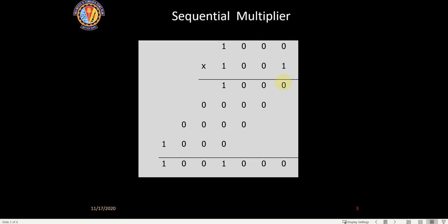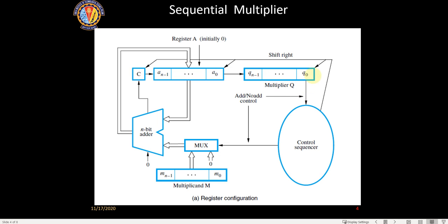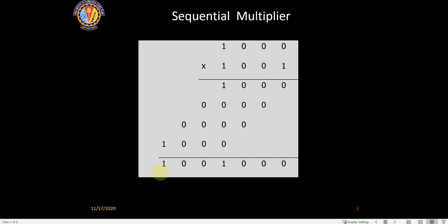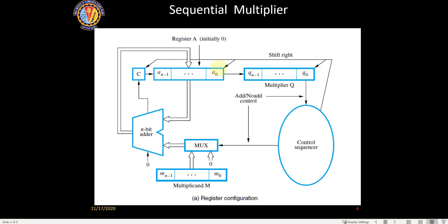So in the third cycle, the third bit is going to be coming here. Likewise, in the fourth cycle, all the 4 bits would have been sensed and the necessary action would have been taken, whether it is to be added with the multiplicand or with 0, in the 4 cycles. Another thing which happens at the end of the 4 cycles is that this entire product will be available from here to here, because that is being pushed out. So this multiplier information, whatever was earlier, is also not available now.